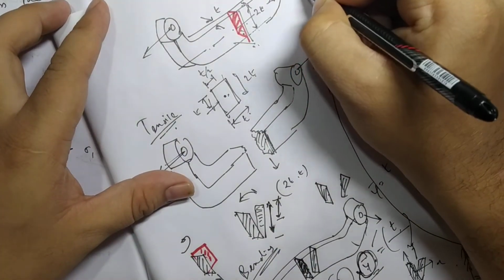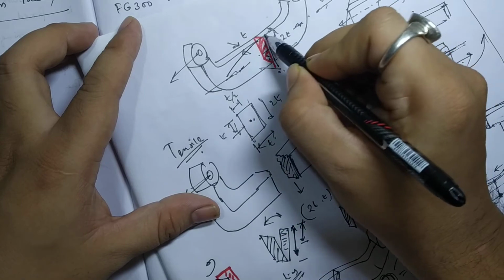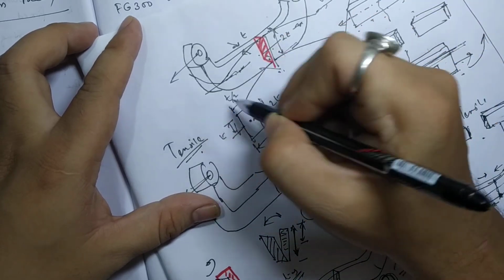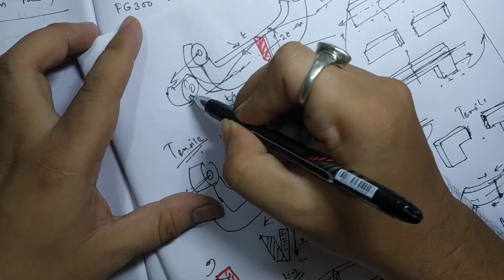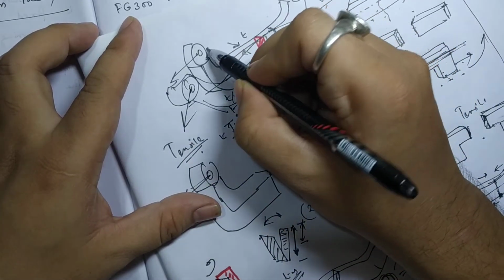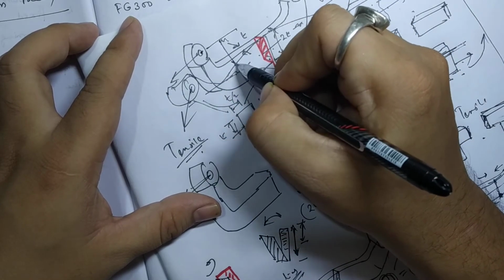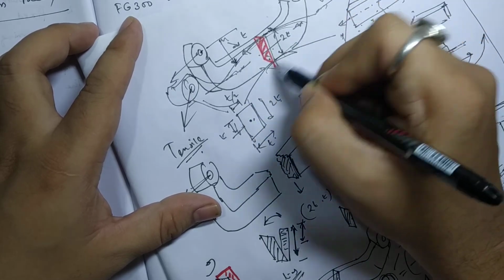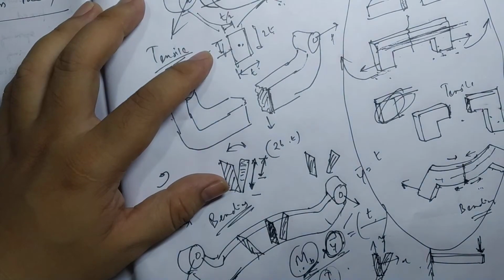Not up to this axis, actually it has started bending at this point. Okay, here like this, right? So the force multiplied by distance from the center up to the top surface, where maximum tension will take place. Here compression will take place, here net tension will take place. Actually ultimately you have to take the maximum bending stress.